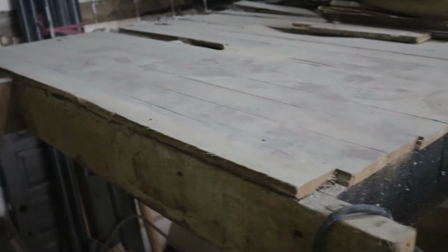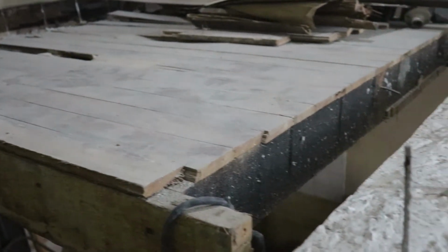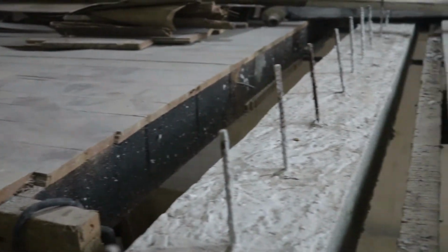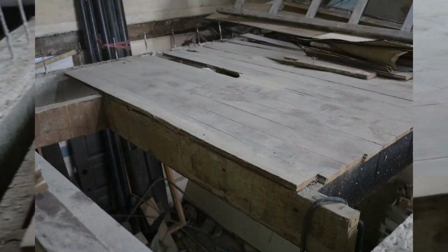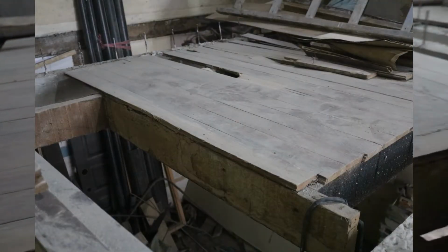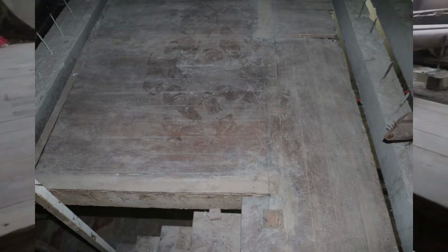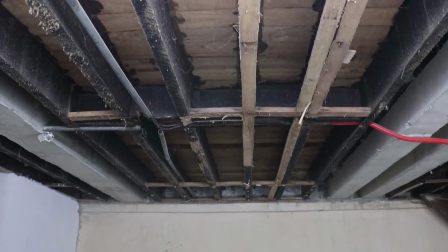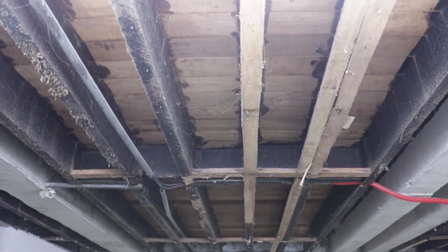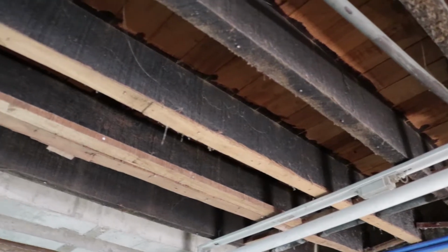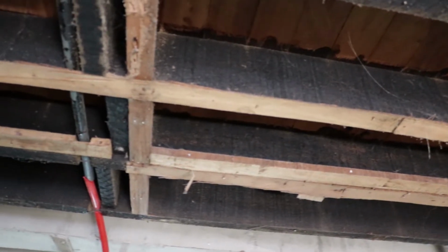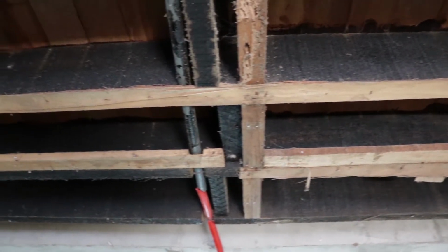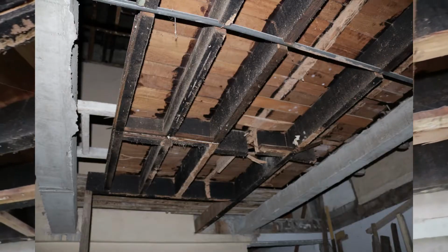However, the second floor floorings were not built from concrete slabs. The floorings are actually built from wood planks, which then are positioned on top of the joists. The joists are 2 inches in width, 6 inches in height, and have a span of 12 feet long, which secondarily holds the floorings of the second floor.